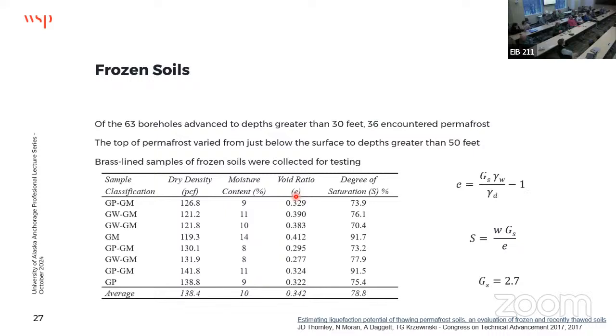I think the preferred method to build buildings in the North Slope oil field is pile foundations. They drill a hole first, and then they put the pile in, and then they put a slurry in that freezes back. The slurry is a sand slurry. And then of course, they try to keep it frozen with thermal siphons.